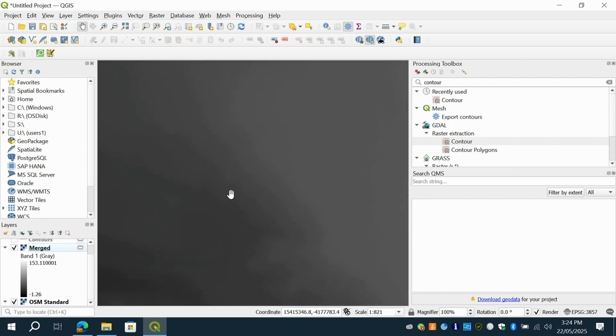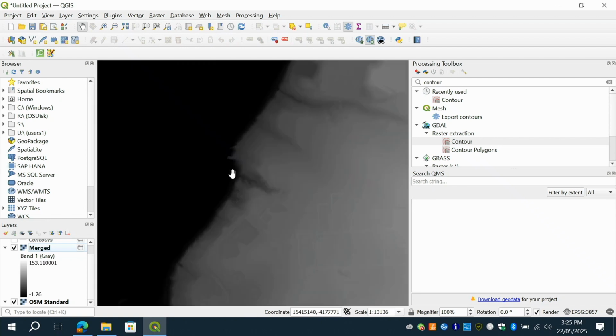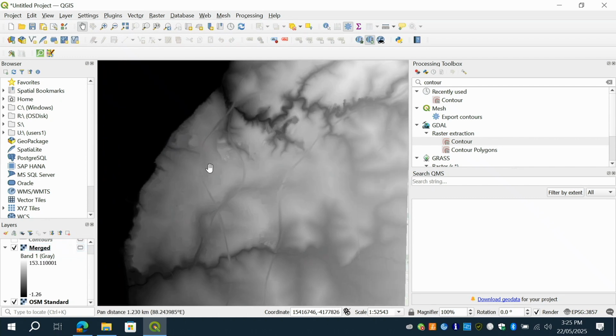For example, if we zoom into the raster layer, we can see very vaguely it's made up by those little squares of 50 centimeters by 50 centimeters. Now we're going to work on extracting the points in the center of each pixel. And these points will represent the height level, which is the elevation level. We can also call it Z level of each pixel.